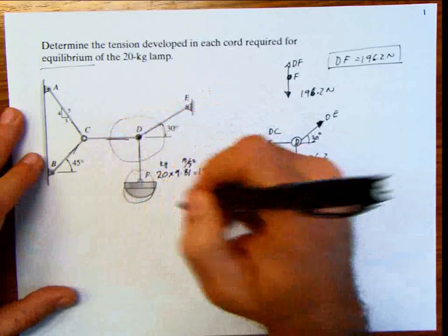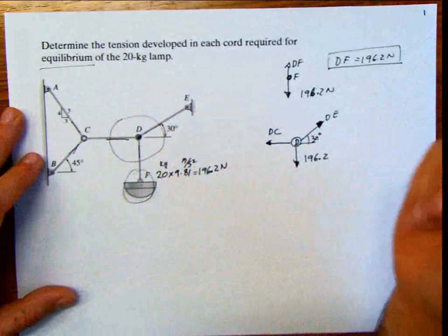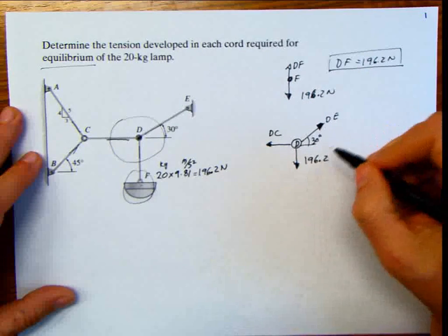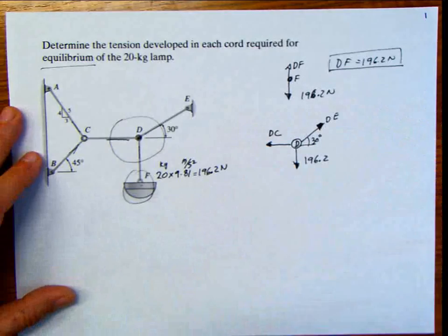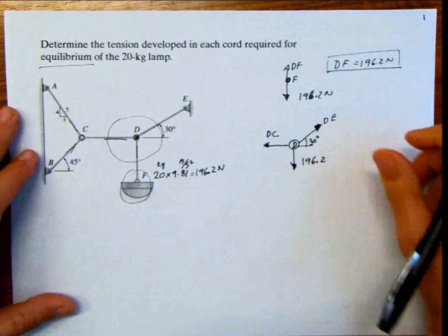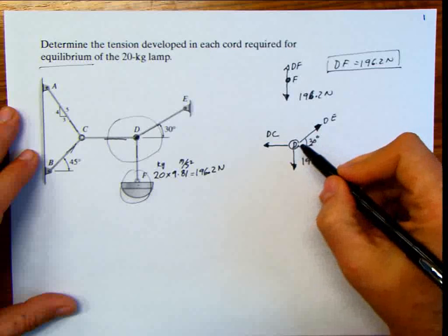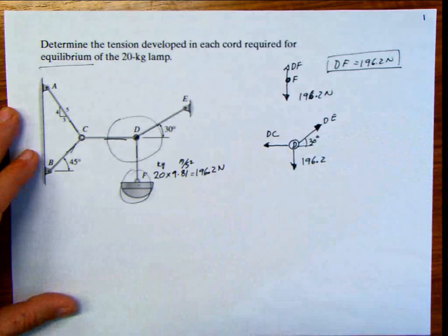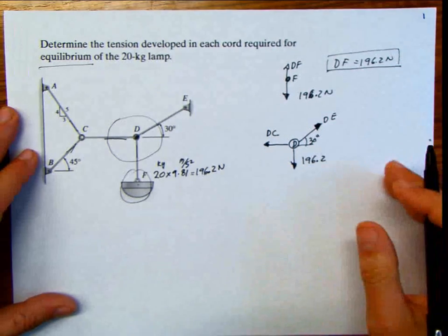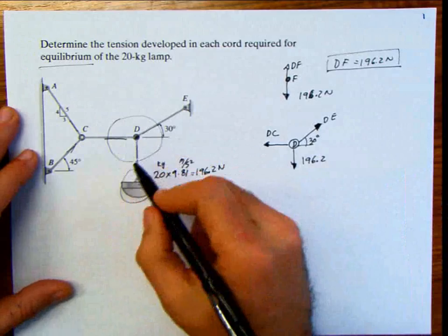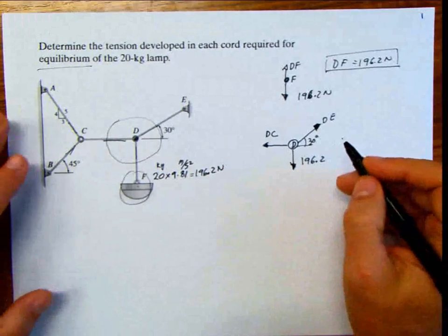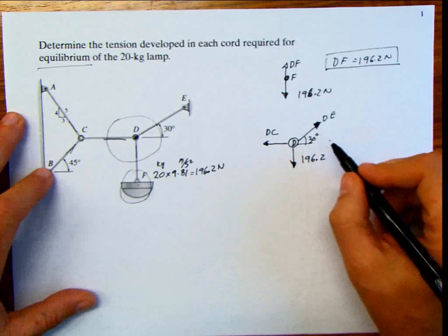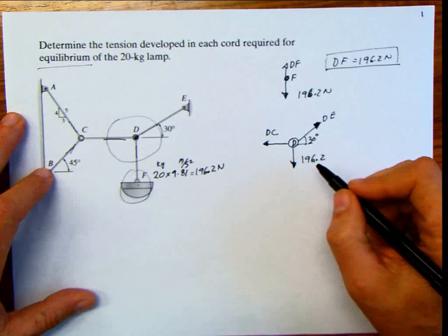If those, instead of being cables, were rods, let's say steel rods or pipes, the direction of these forces could be different, but it doesn't matter, because once we go further into the program, you're going to see that I could assume the direction going down, for example, but the result when I get it is going to be negative, and that's going to tell me that I messed up with the assumption, basically. But in the case of cables, you always put the cables in tension, because it's the only thing they can do.